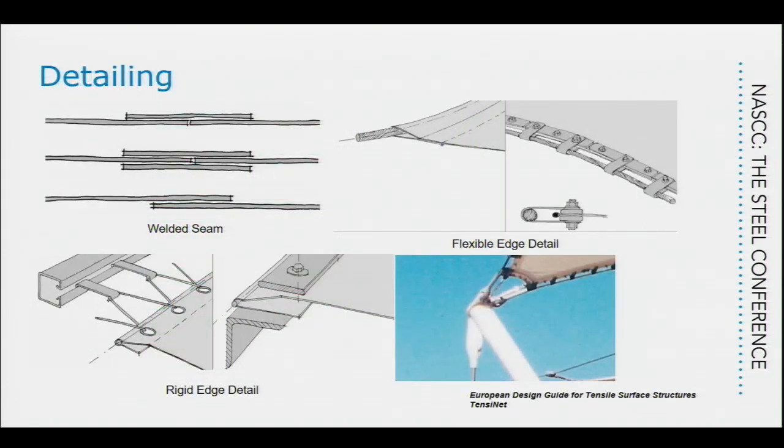So I put this slide of detailing here right after patterning because, yes? Sorry, can you thicken it to make up for that difference? Yeah, so you can thicken it. What happens is, if you thicken it, when I keep the exact same strips, your curve is less dramatic because it's a stronger material that deflects less. So you have to kind of start the form finding process again.